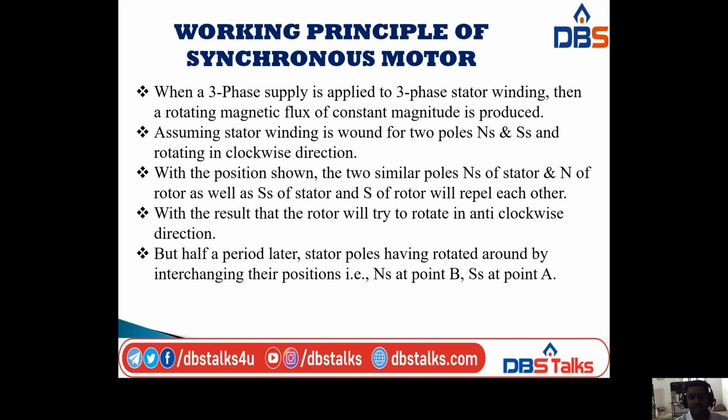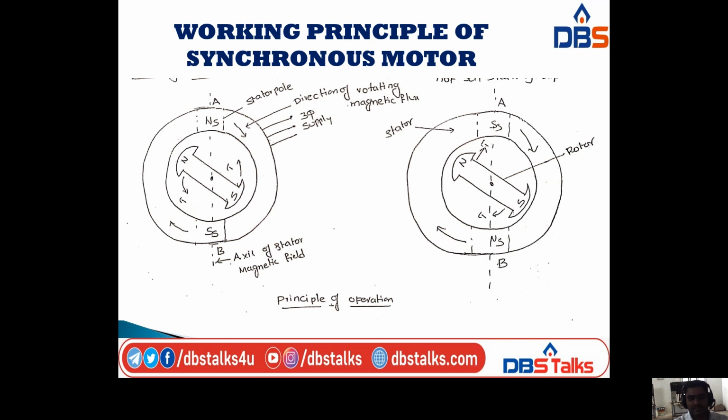Here I am assuming the stator winding is wound for two poles, that is N_S and S_S, rotating in the clockwise direction. So I will show the diagram, after which you will understand this. This is the working principle diagram, the principle of operation of the synchronous motor.